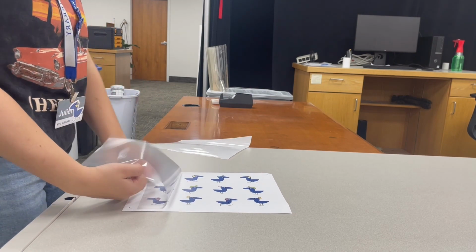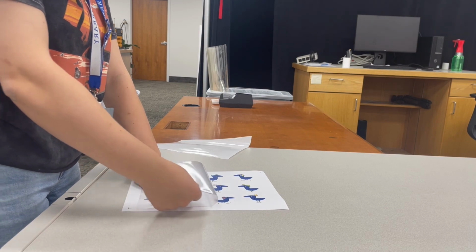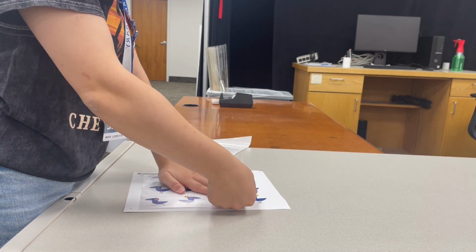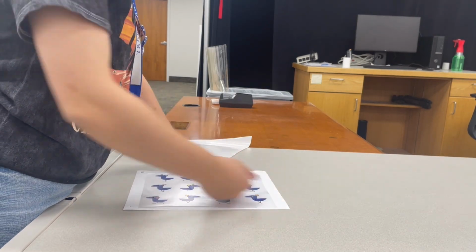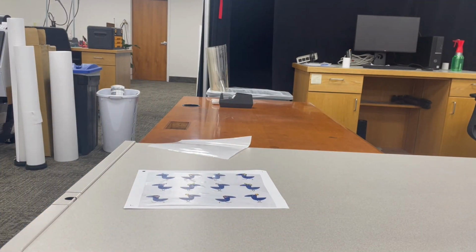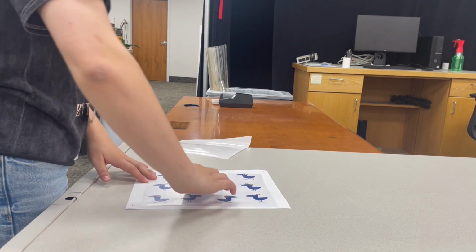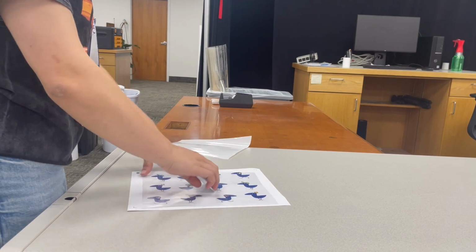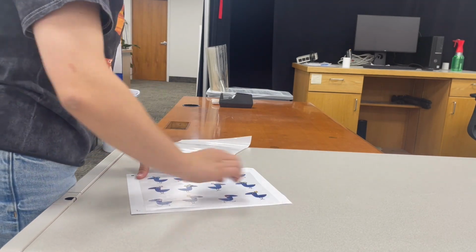The UV doesn't have to cover the whole sheet, just anything that will be cut. To apply, peel off the backing of the UV coating. Then avoid creating bubbles under the UV. Set it down on one side, and then gently stick it down, moving in one direction. Once you've done that, to help remove any air pockets, take something with a flat edge, preferably the flat scraper in the Cameo tools, and push it from the center to the edge.